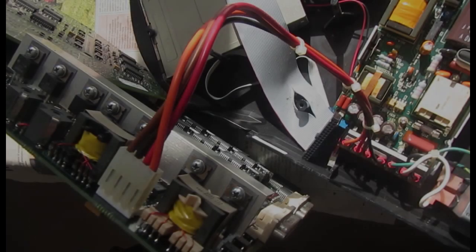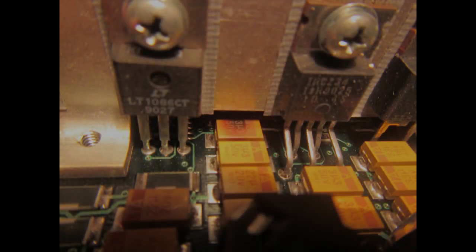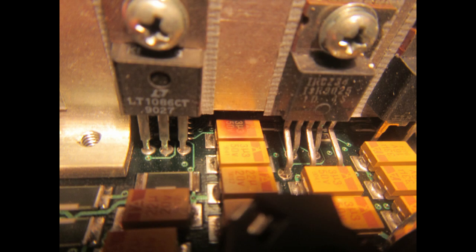A device programmer like this needs many different DC power rails. In this case, the engineers choose to have a single supply voltage, which is 15 volts, generated from an offline switching power supply, and then a set of DC-DC converters located on the main control board that generate all the needed power rails. In this unit, the 15 volts from the main power supply are present, but almost no other rail is present.